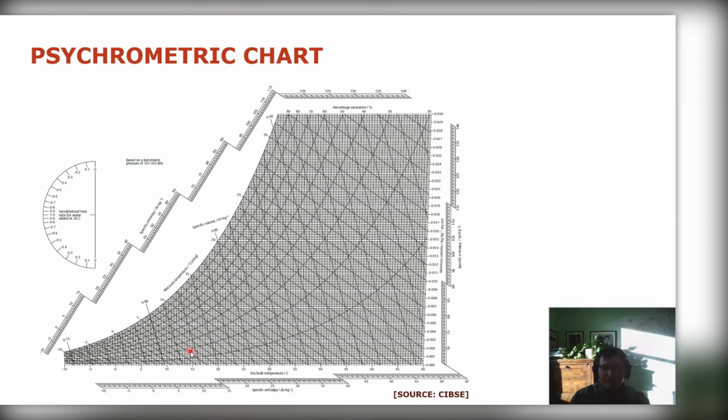And as you can expect, when they're working harder, the amount of sensible heat actually changes little, because their body temperature doesn't really go above 36.6 that much, but the amount of sweating and perspiration they give out increases dramatically. The other thing to consider is how they're dressed. So in a clean room, if they're wearing sort of paper overalls, most of the perspiration would stay within it. So then you can probably ignore a lot of it. It will be mostly the face that it will be coming from.